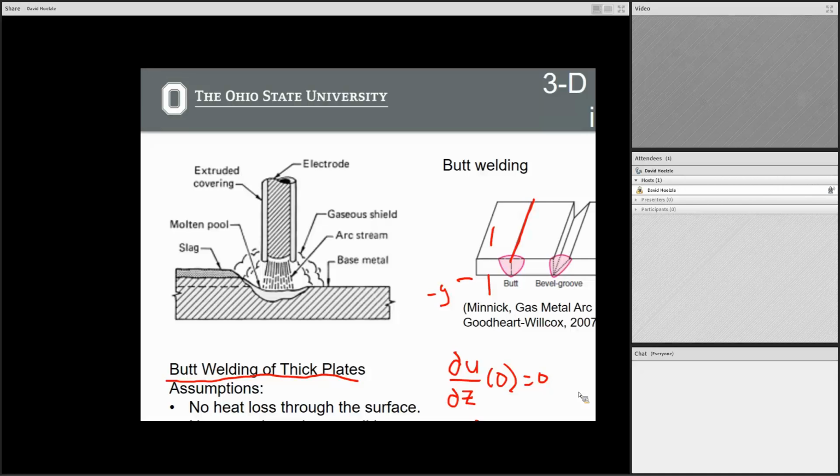Radiation. So, I guess that's not because it's not a laser, it's a plasma. But it's still the case that the surface is hotter than the environment, right? So you still have radiation. Radiation is basically heat loss via photon transfer. So anytime you have two different surfaces of different temperature, you have radiative heat transfer between those two surfaces.